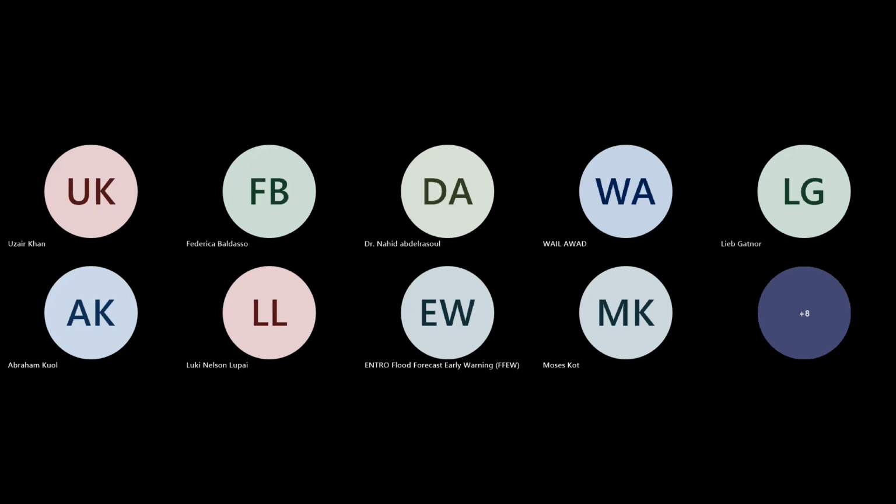So you have seen there are, for a one-dimensional model, at least two ways to create the geometry. When you have cross sections, you would go for the classical geometry data editor, importing or adding the cross-section data. When you have a DTM, you might want to use the RAS Mapper, which is a GIS embedded into the RAS model, the same thing that you found in HMS, where the basin delineation component is a sort of GIS embedded in HMS.